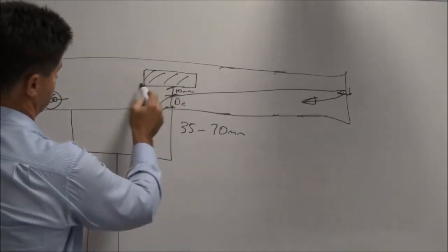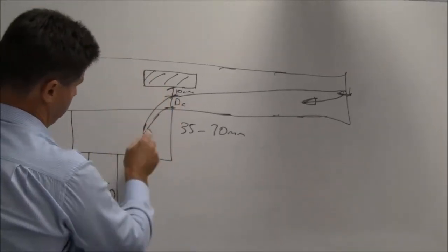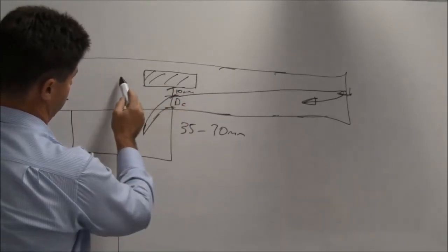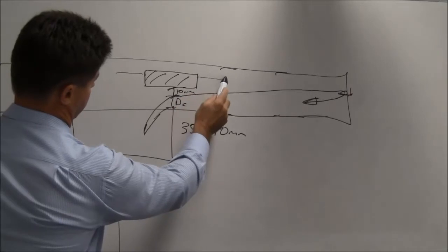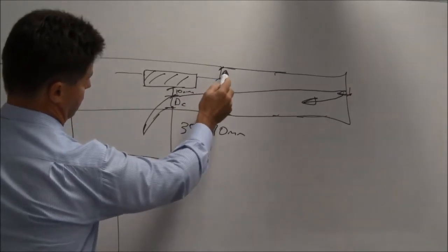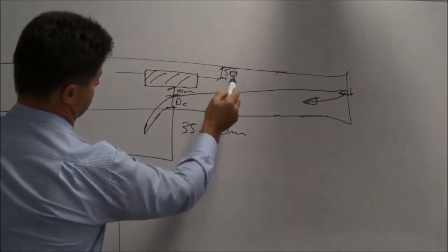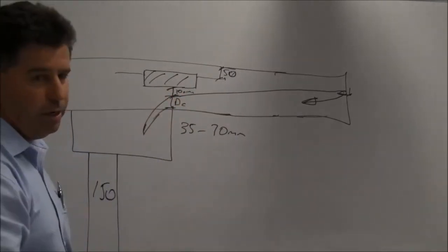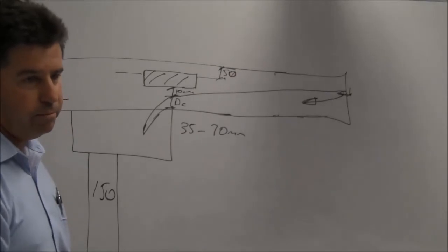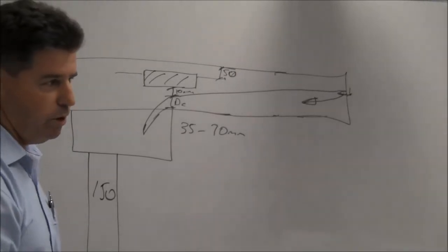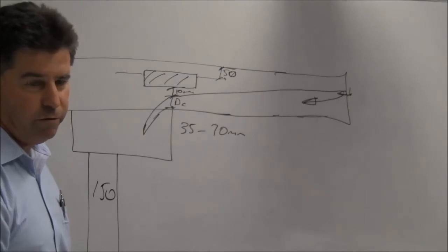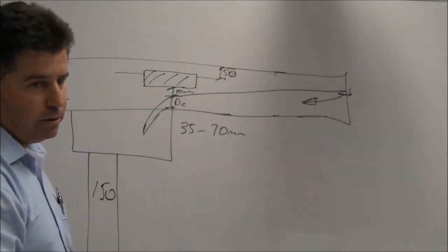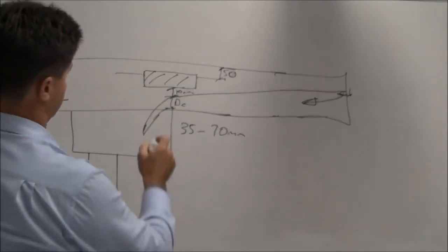Yes. Then obviously, to get the same amount of water that we want to discharge here, if this is completely blocked, we have to come up with an overflow that's going to work while still maintaining our freeboard, our 50 mil. We still need to make sure this overflow will carry the same amount of water that we're trying to get down this blocked downpipe. Okay, we must provide 100% full overflow capacity on a box gutter. Does that make sense? Yeah, that makes sense.